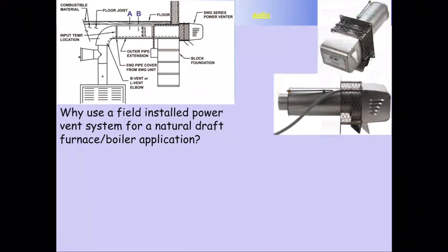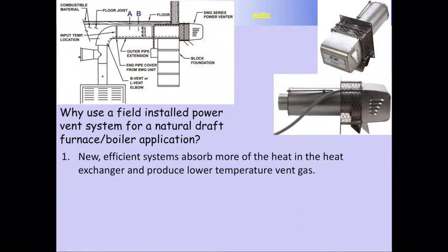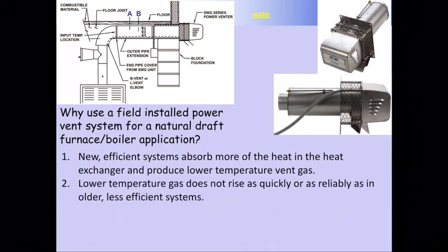So why would I want to use one of these? Why would I want to use something like this to do it? So it could be, maybe your new efficient system absorbs so much more heat in the vent, or in the heat exchanger, that we produce lower flue temps. It's going to ensure that I have proper draft. That might be one way.